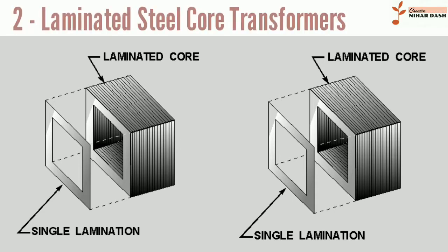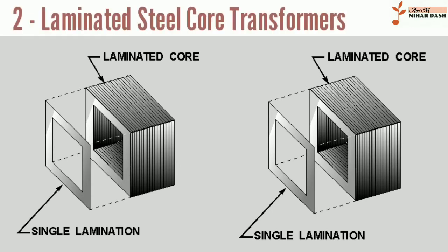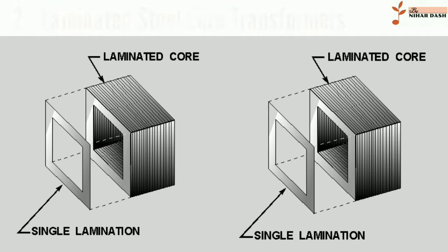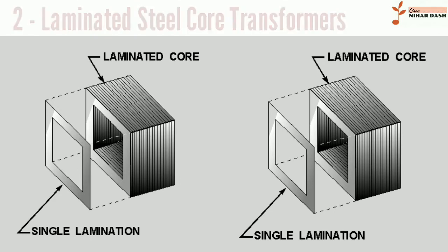It is then cut in two, forming two C-shapes, and the core assembled by binding the two C-halves together with a steel strap. They have the advantage that the flux is always oriented parallel to the metal grains, reducing reluctance. A steel core's remanence means that it retains a static magnetic field when power is removed.